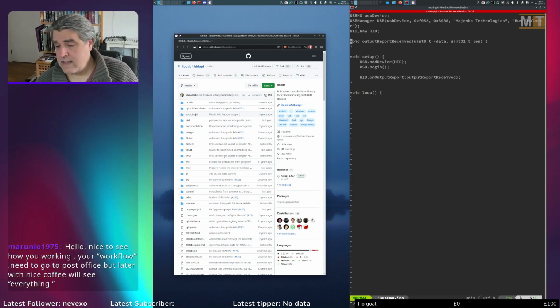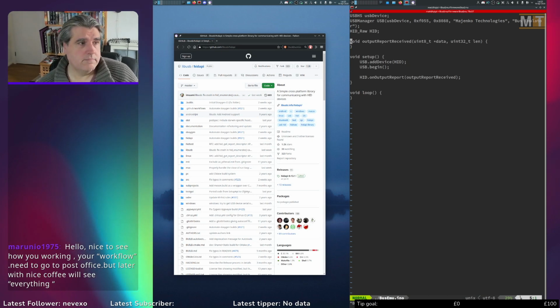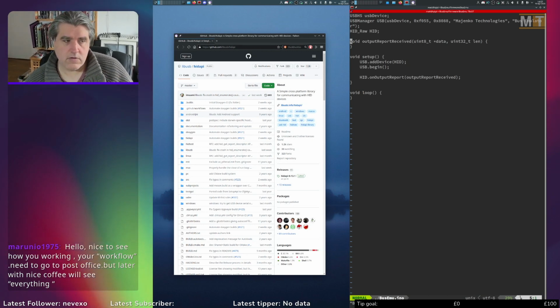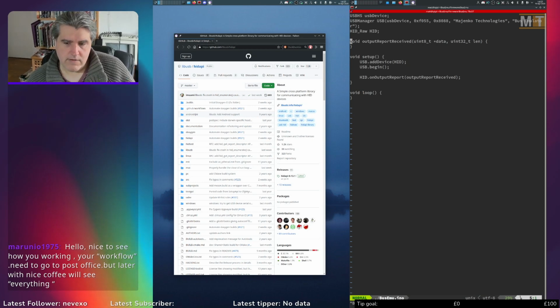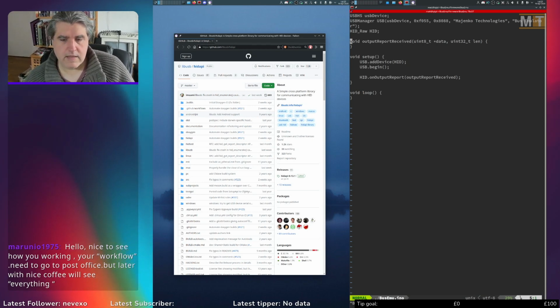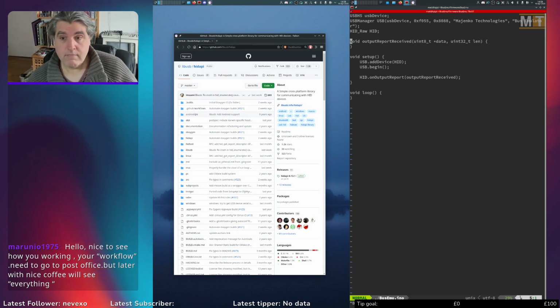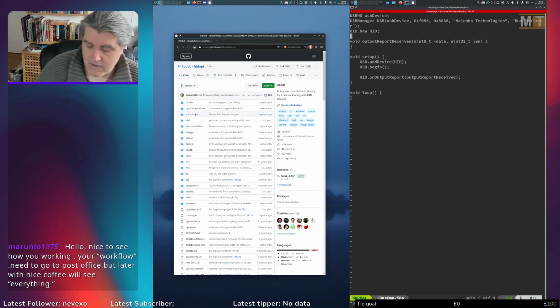The following 7 bits, or a subset of them, can be the address that you're doing the operation on. And then if it's a write operation, a second byte which contains the byte to write. I think that might be how I'll have it.